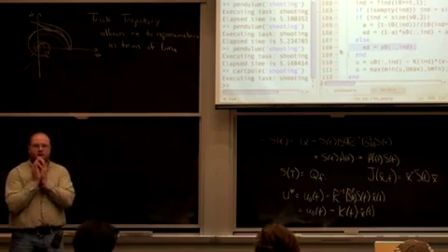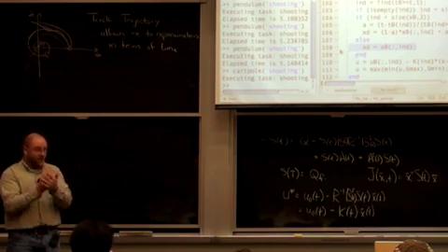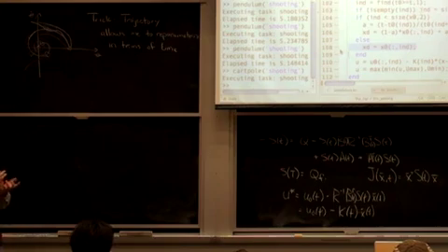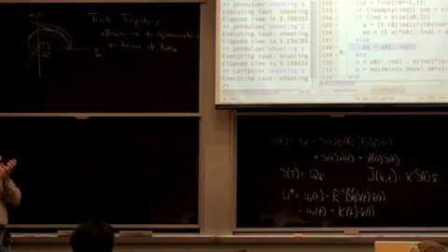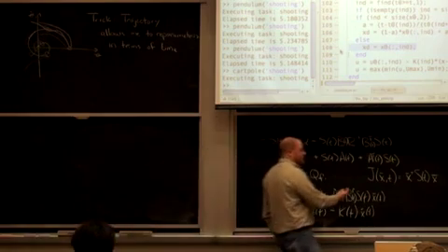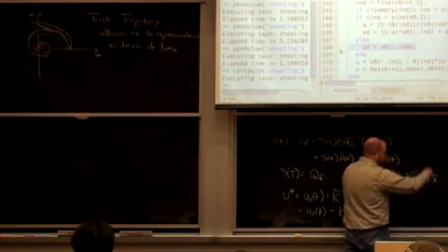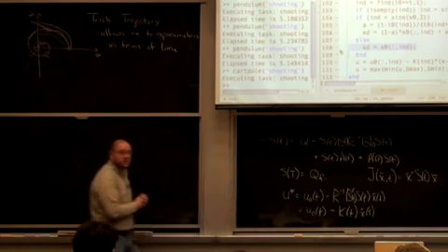Just like the original LQR, you can think of this as a quadratic bowl. In the LTI LQR case, am I okay throwing around these three-letter acronyms? In the LTI LQR case, it was a static quadratic bowl centered around the point I'm trying to stabilize. So my cost-to-go says as I move away from the point I'm trying to regulate, I'm going to incur more cost, and the rate it grows depends on the variables inside S.